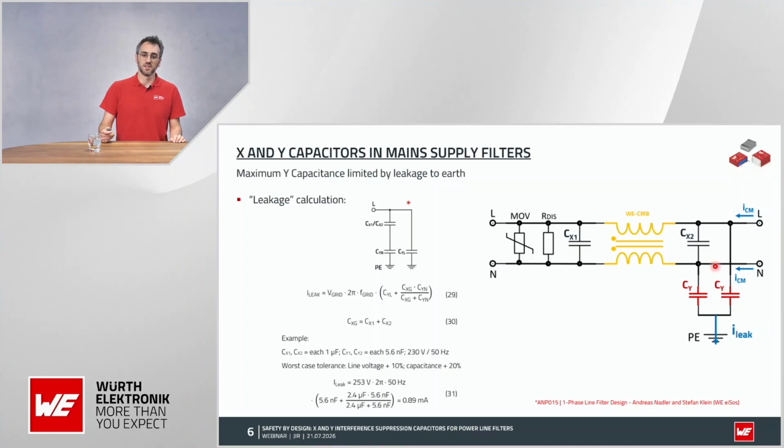It's a property of AC systems, and this leakage current is normally monitored to detect current to ground failure, which could also mean a safety hazard. We are not able to have a lot of leakage current because this will trip the safety systems. And there are very specific and strict regulations about how much the leakage current can be, depending on the application. For industrial or domestic devices, it can be less or more.